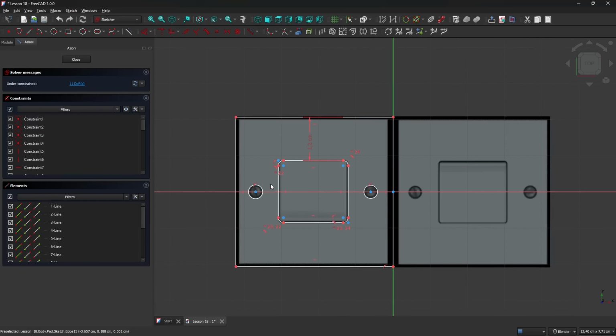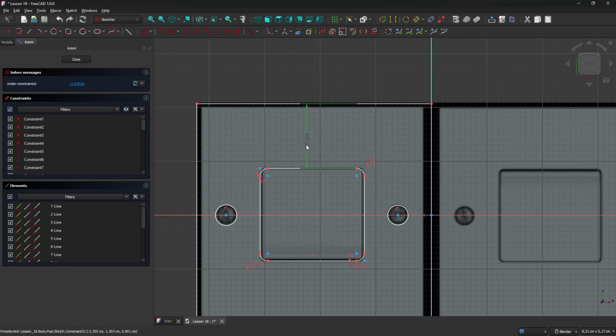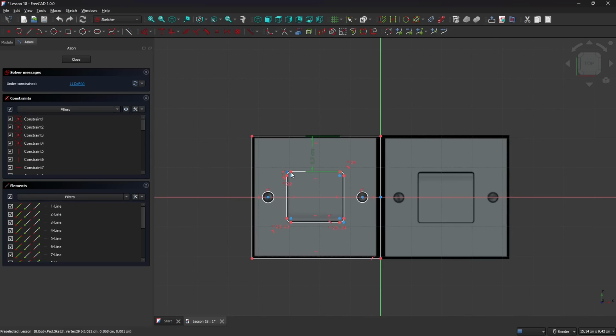So this is a specific way to design in Part Design, which is closer to industrial design and things like that. When you draw a dimension here, it's not just like we are putting some annotation. This is actually constraining our design, our drawing. So it's pretty different from Draft. If your plan is to just express something, present something, and you don't need to actually have constraints or things like that, you can use Draft.